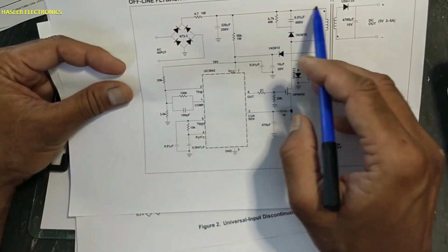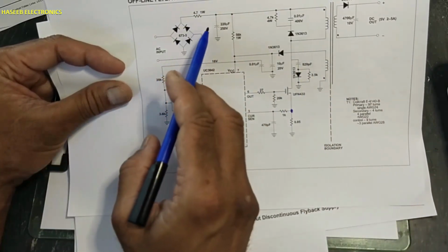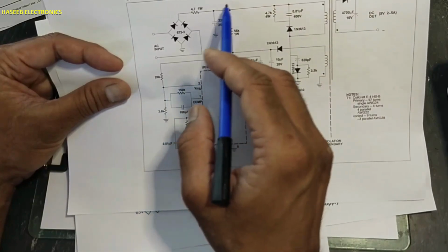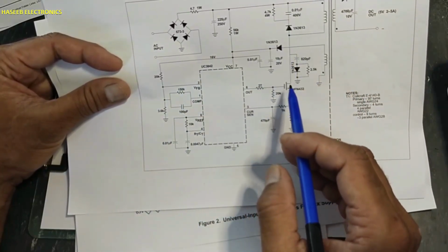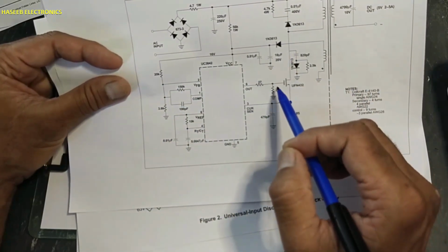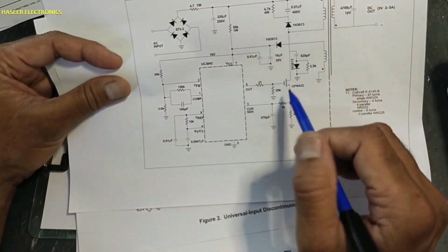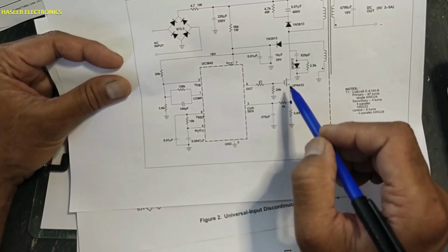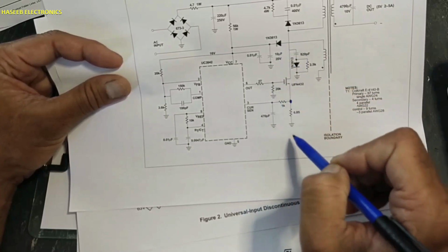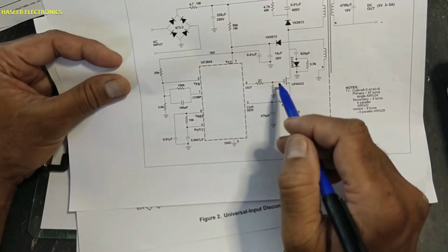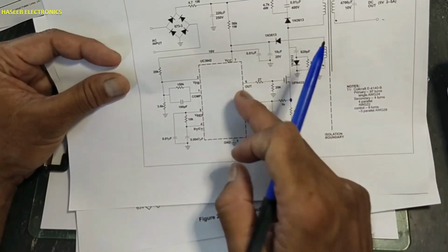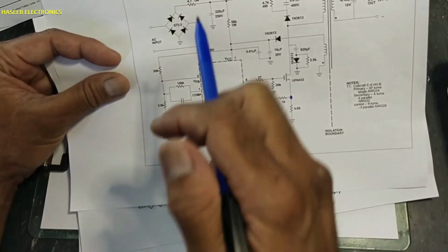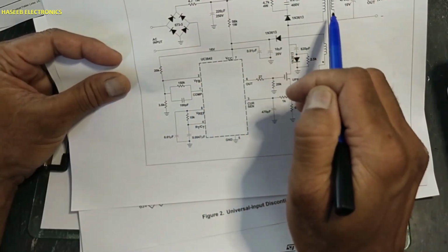So we can see positive voltage stored here and its ground side is connected here. So current will flow in this path if the MOSFET is on. If the MOSFET is off, then there will be no current flow in the circuit. That means we need some signal to turn on this path, to close this switch. For that purpose we need a drive signal from this IC. It is driving the gate. This voltage is provided to the transformer.